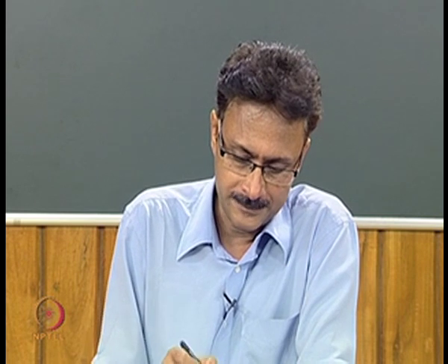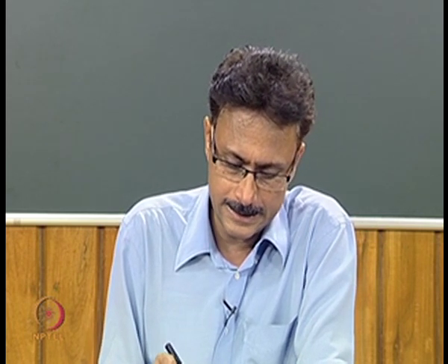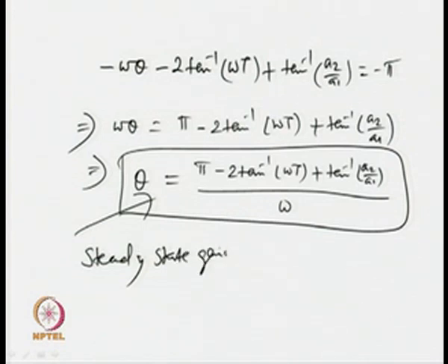So, this procedure can be applied for any transfer function model. Of course, the transfer function model should have a limited number of unknowns. Now, for this transfer function model we also have 3 unknowns theta, t and k, and k, the steady state gain, can be obtained again from the ratio of the average value of the output signal when you have got relay in the loop and the average value of the input signal.